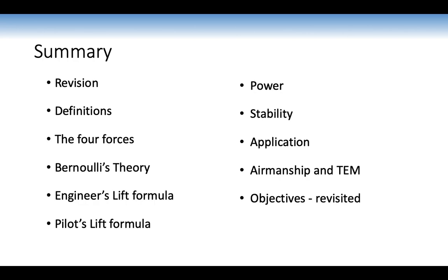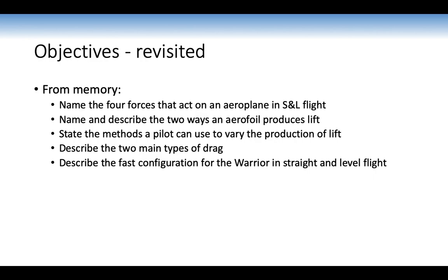The application, make sure you know those 4 configurations well for straight and level flight. Airmanship, threat and emergency considerations, make sure you watch out for traffic, watch out for weather, and you extend that flap at or below the white arc range, and you monitor that power setting so you don't redline. And then finally with the objectives, I'll give you a moment, you can pause the video, and then I'll read out the answers.